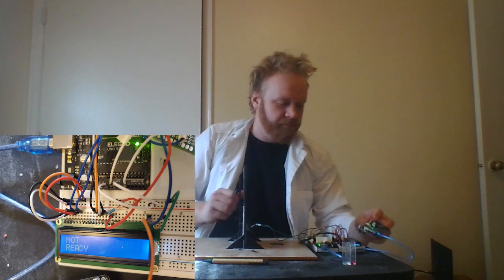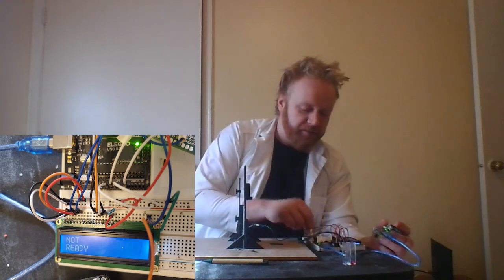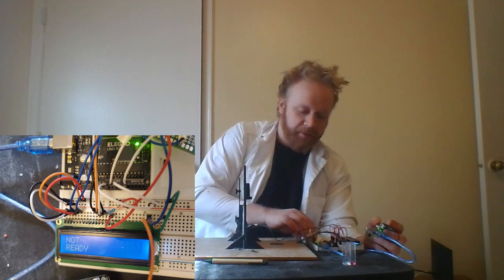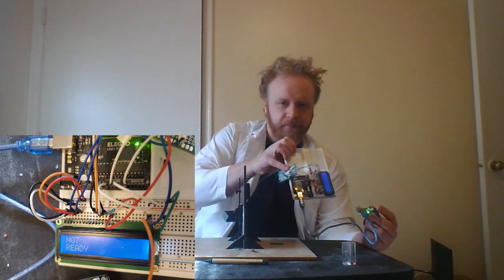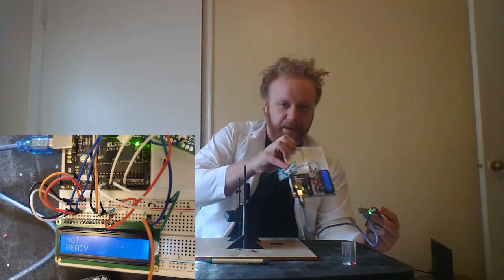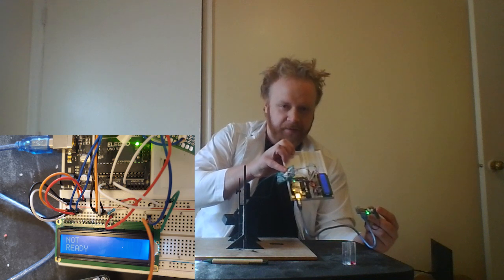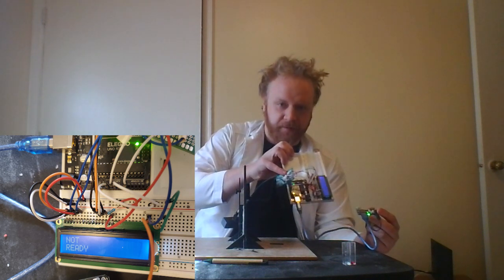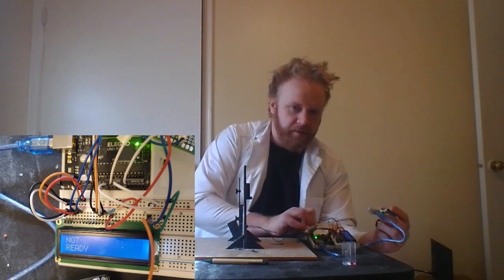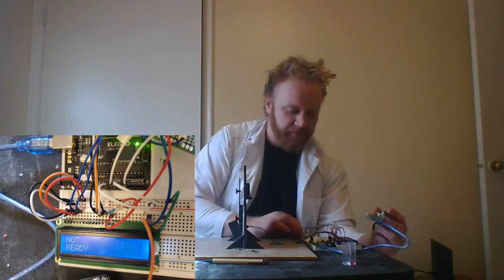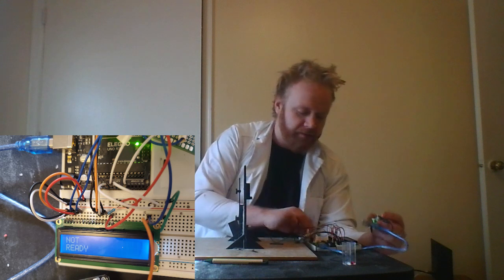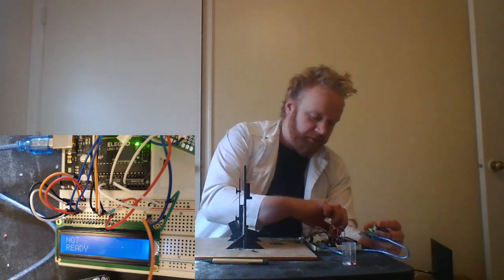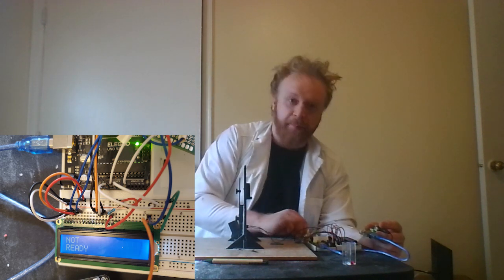The electronics here are actually not that involved. The majority of what you see all these wires for is to run my LCD screen. Just so you have a better understanding, this is our Arduino component here. It is storing all of the power supplying and all of the equations. It's calculating the voltage through the resistor and then turning that into an absorbance for me. It's also saving our blank. I do that simply by working a switch over here, and by switch I mean I have a wire that I plug and unplug.